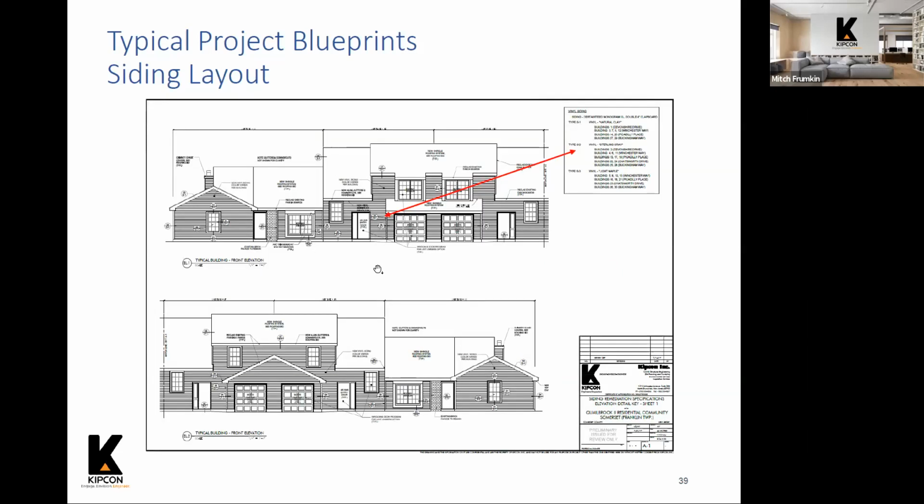So sometimes the details require a little bit of a diagram showing what each area represents. So this particular one is an elevation detail key, which shows if you're in this area of the building and you're installing vinyl siding, how should that vinyl siding be finished around a window or around a door, per se. And then you'll see those little bubbles, those callouts tell you what number detail and on what sheet to refer to see how that vinyl siding should be finished in that location.